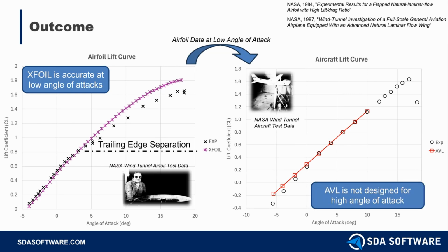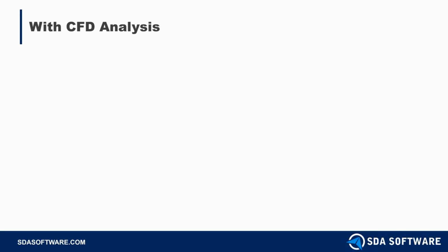But we shouldn't really push this to the far right where you have a high angle of attack, since this tool is not designed for high angle of attack, and specifically the imported airfoil data is only confident at the low angle of attack. So even though these tools are amazing at the low angle of attack, this still doesn't really picture the whole story. So let's see if CFD can capture the big picture.